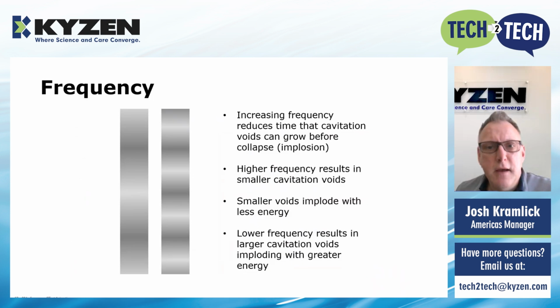Increasing frequency reduces the time that cavitation voids actually have to grow before they can collapse or implode on themselves. This higher frequency results in a smaller cavitation void, and those smaller voids implode with less energy than larger voids. In contrast to that, lower frequency ultrasonics obviously create larger cavitation voids, imploding with greater energy.